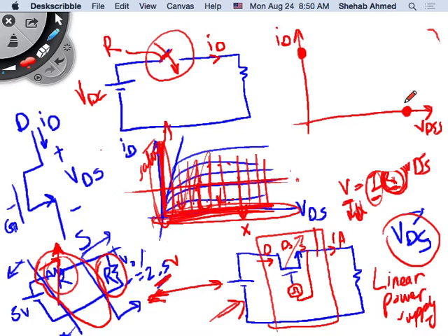Because in real life, when you have voltage across a device, any device, if I have voltage across any conducting material, anything, then there will be some leakage anyway. Even across a capacitor, right? The capacitor is supposed to be two plates with a dielectric material. This dielectric material has a leakage component to it. And this leakage may change with temperature, may change with the value of voltage, etc. But it's a leakage current, right? So we will forget it for now. We will not be interested in it for now in our course.